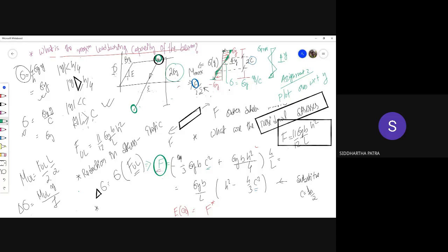The red curve is the stress distribution after the loading process. The green curve represents the change in the stress distribution after unloading. The net stress distribution is on the right, which represents the residual stress.